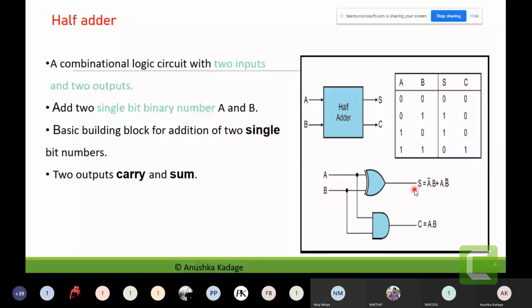While defining the gate implementation for this carry, if I observe when the two inputs are 0, or any one of the inputs is 0, the generated carry value is 0. But when both the inputs are 1, the generated carry is 1. So this is exhibiting the behavior of an AND gate. So to implement this C output variable from the A and B input variables, the AND gate implementation will be done. And that AND gate has been presented over here.